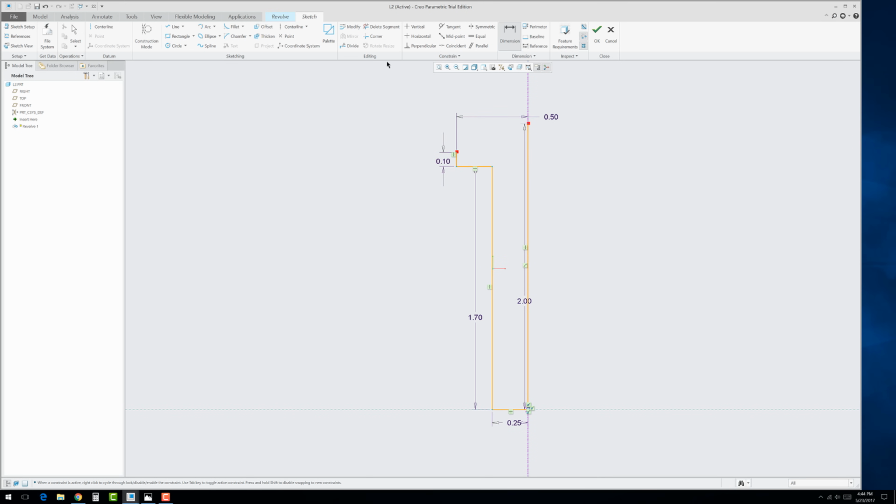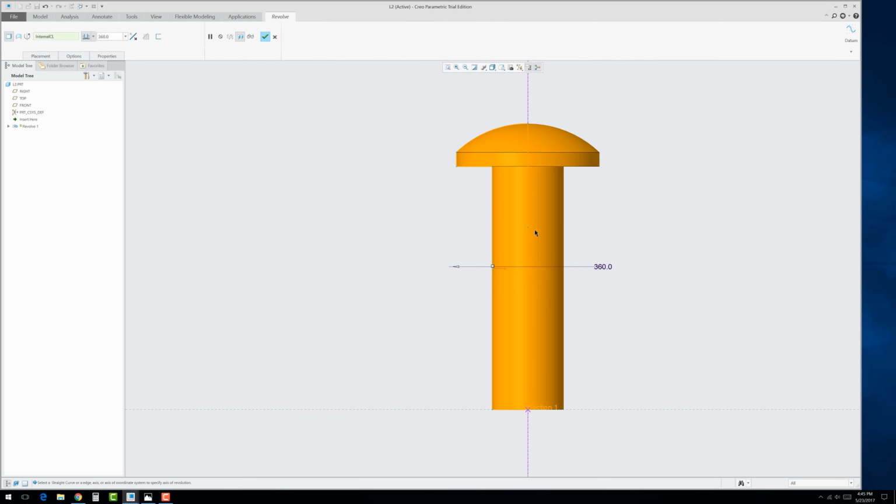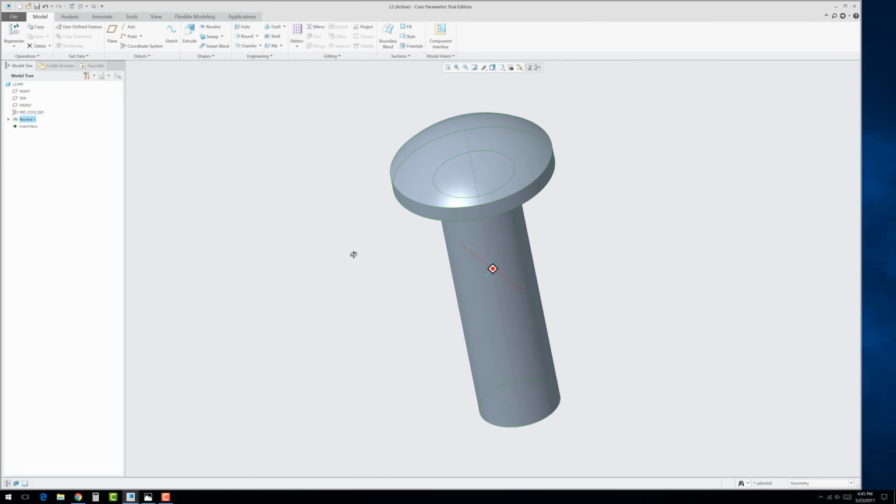because we're looking at the radius. Now go to the arc tool, make sure you are in 3-point arc, connect those 2 points, and notice down below, look at that, it snaps to center, and you get that little symbol in the green box. That's perpendicular. Perfect. Middle click, and then middle click 2 times, and voila. Let's go to dimension, and actually I don't think it needs it. It's fully defined. Never mind. Okay, so with that being said, hit OK, and it should revolve 360 degrees.